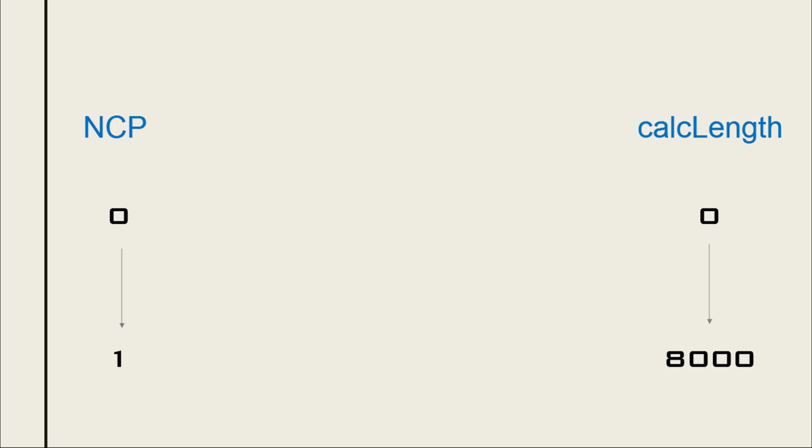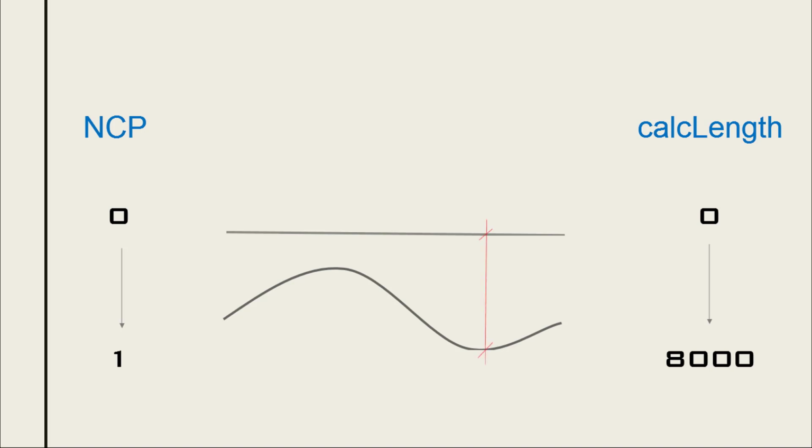If we have the plane where our panels are being placed, and we have a curved surface that we'll manipulate to change the form, we'll have to know how much we're going to deform this surface so we can give it an approximate number. So let's say that this length will be up to 8,000, meaning that anything above 8,000 won't transform our panels anymore. So we want this normalized curve parameter to vary between 0 and 1 when this calculated length changes from 0 to 8 meters. So the math.